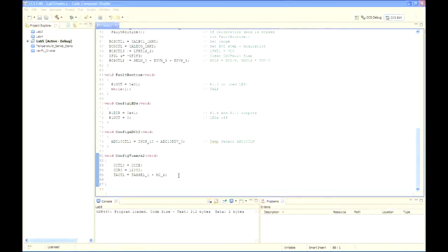Reference the user's guide and the header files and notice the following: TACTL, that's the timer A control register, the TASSEL1 selects the A clock as the input, and MC2 sets the operation for continuous mode. When the timer reaches the value in CCR0, the capture compare register 0, an interrupt will be generated. Since the A clock is running at 12 kilohertz, the value in there needs to be 12,000 cycles if we want it to go off every second.